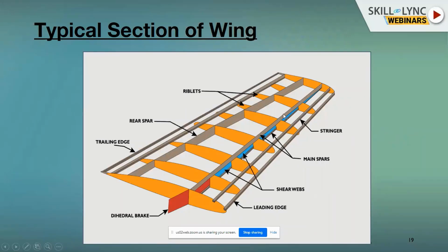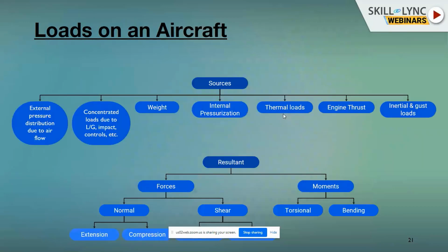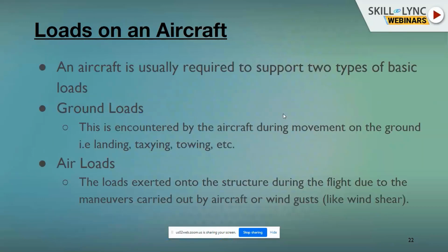So there are certain things like the landing gear. You cannot have two landing gears. If one landing gear fails, it's failed. That's how the structure is designed. They call it safe life. Once the life is over, stop it. And another is fail safe.